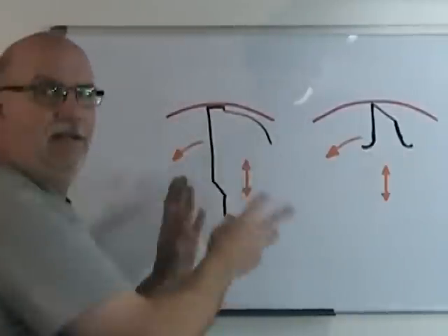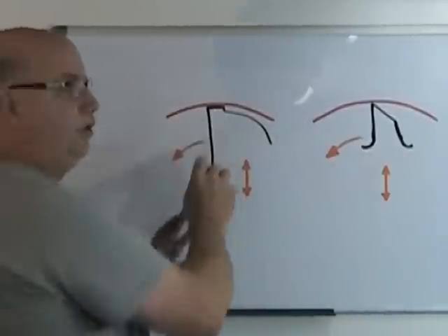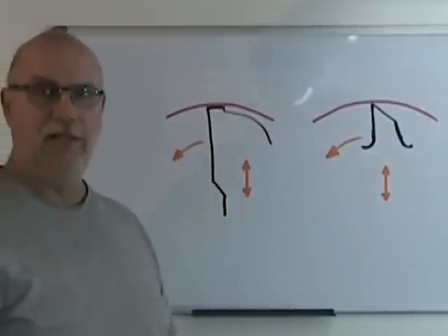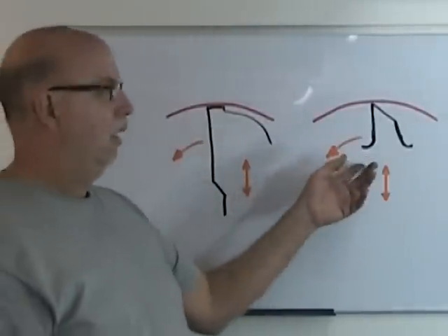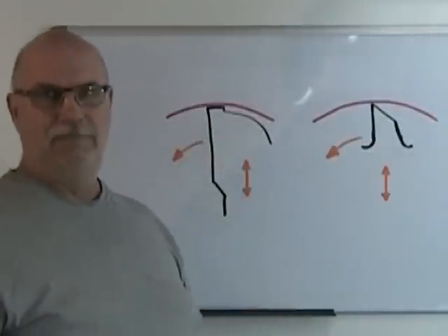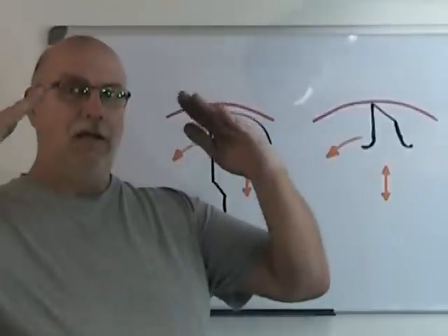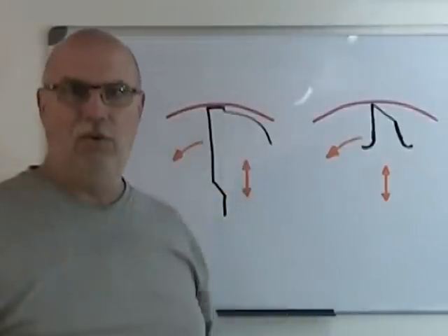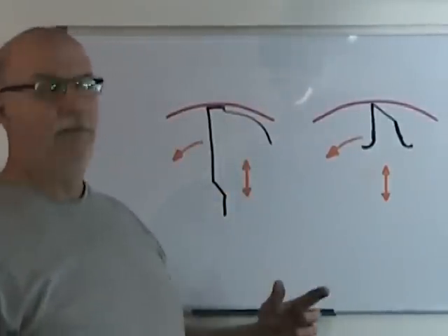We now have an idea of why the margins here are rounded out and why we have our chisel edge there to track. Our reamer doesn't have that. It has a 45-degree angle on its end. Remember, we saw that in the part 2 video of this lesson 8. And it's that 45 degrees that keeps the tool tracking in the hole that it's penetrating into.